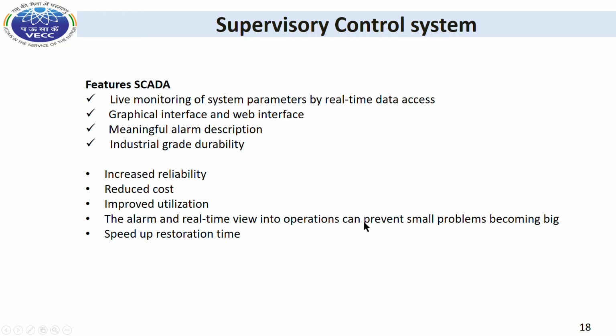DCS consists of one or more local controllers, and they implement advanced process control techniques. But SCADA cannot carry out advanced process control techniques. Advanced process control is generally handled by the very local controller, the PLC. SCADA software generally monitors the overall performance of the loop.